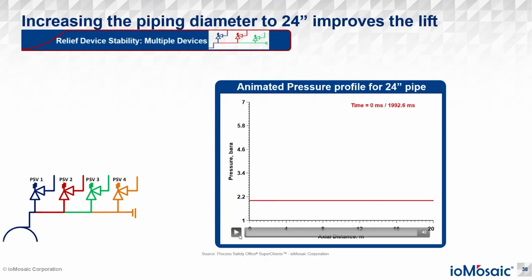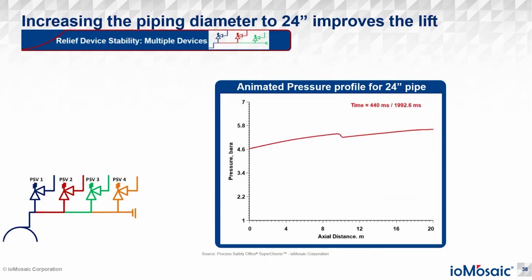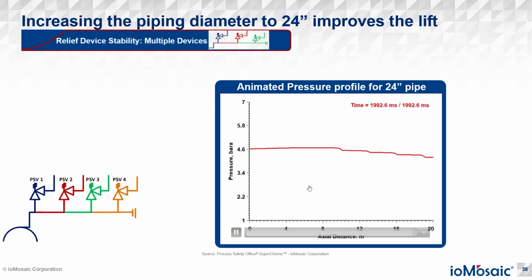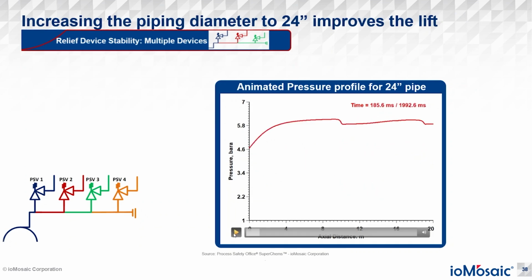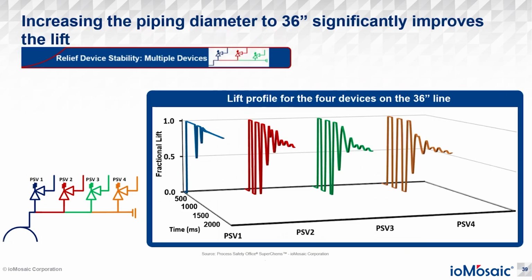We can also see a bit of that hopefully in the pressure animation. So if I just run this a bit, okay, it's continuing, and you can already see the pressure isn't going up and down as quickly and as rapidly as previously. And we can even see it calming down quite a fair bit here. So again, just a bit more of a fluttering motion, not so much of a chattering motion, which is exactly what we want. And then just to prove it a bit more, I went up just slightly higher, and basically the fluttering just disappears.